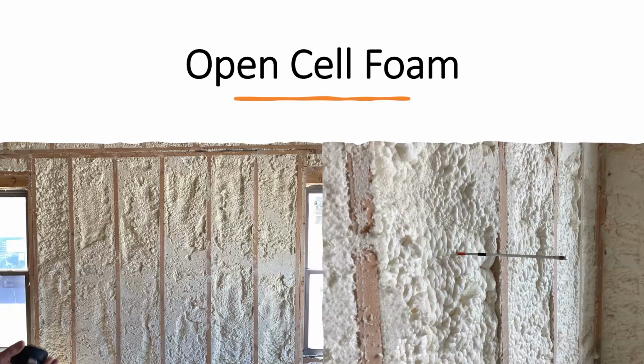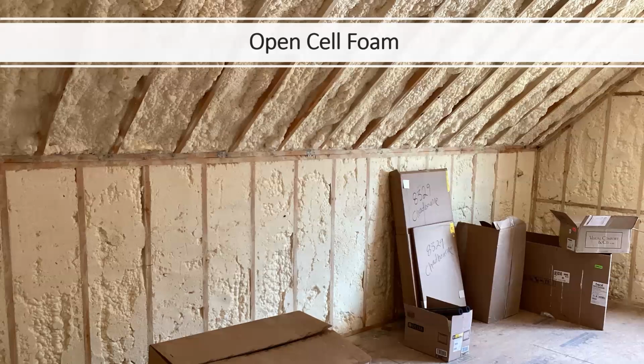And so here, looking at that, I've deemed that as a grade 1 install. It's touching the bottom of that orange tape. That's a 3.5 inch depth. They're meeting the R value per inch as an R13 wall. On the left-hand side, they've got a few pockets, but overall, that's done very well. They've achieved what they needed to in a grade 1.